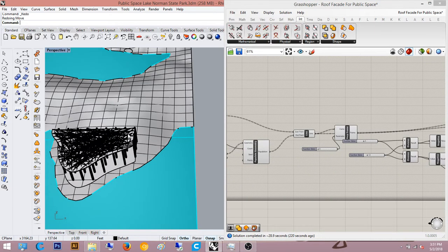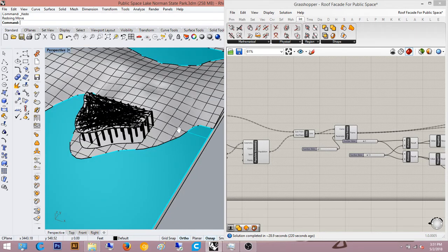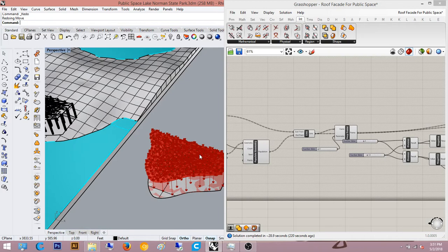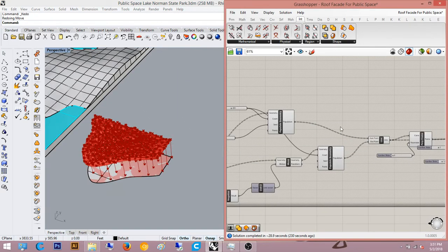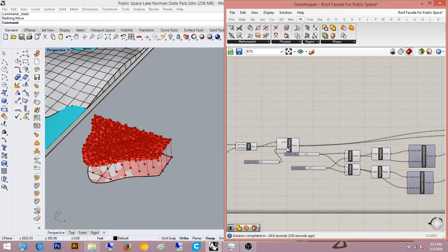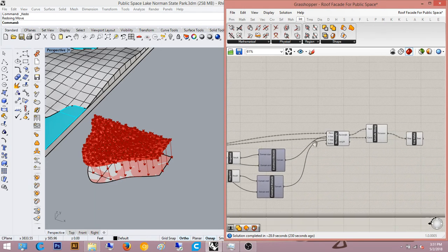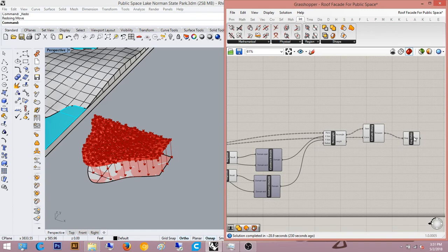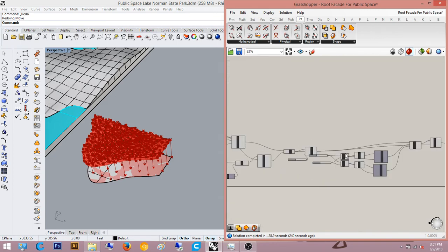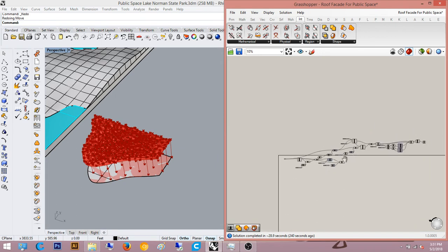I already moved and baked it, as you see, so I'm going to close out Grasshopper soon. I took the surfaces, moved them, did a populate 2D for both, made sure they're both the same number, drew a line, had my perpendicular frame, drew a rectangle on that frame, extruded along the curve and then made it solid. Nothing fancy.